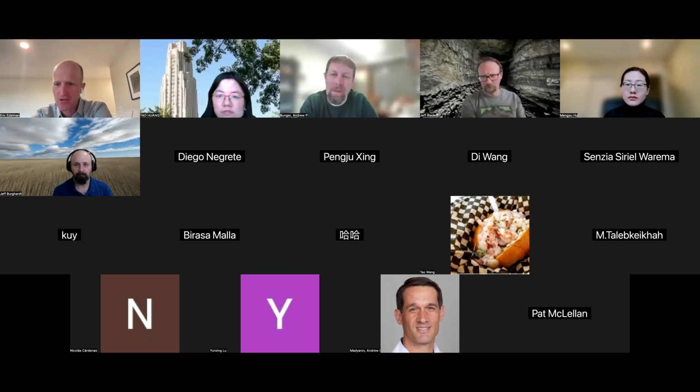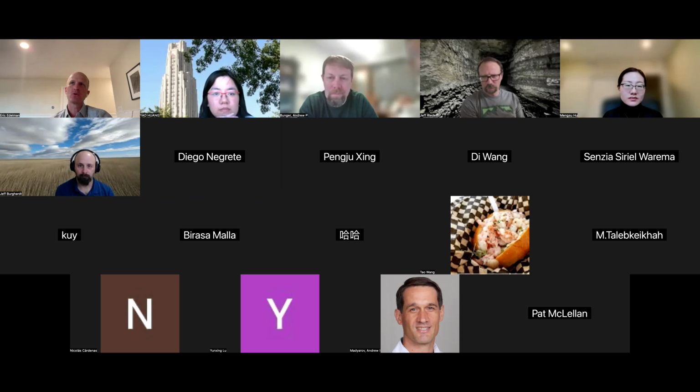Andy, I got one more. With your delayed fracture initiation work, have you tried a hysteresis effect, like stress cycling them, loading it half the duration of what you assume to be the length of failure, backing it off, reloading and waiting? We worked on this 10 years ago with Gallium Adagurov. Really excited to see the progress that you've made, but what interests me is, from a cycling standpoint with the time dependent nature, whether you get the same acoustic emissions.